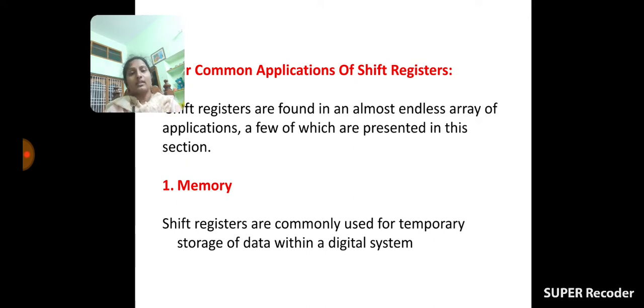Only one register has the capacity of shifting the data in both directions. So no, two registers are not used. If a bidirectional register is there, it is able to shift the data from left to right and also has the capacity of moving the data from right to left. Simply, it shifts the data towards left, and also towards right.